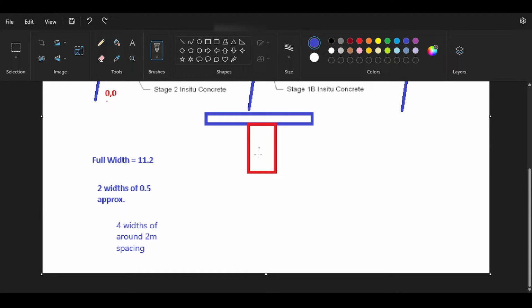Now the beam is a pre-stressed beam, so the cracking will be limited because we will see this in the future, but the stresses are controlled in such a way to not exceed the cracking stress of concrete for the pre-stressed beam. However, for the slab, you have simple reinforced concrete, meaning that the slab might crack. Now, when does the slab crack? The slab cracks if you have a negative moment, or as they call it, I think it's called a hogging moment. Because that's our bridge now, that's what you will have for moment diagram in a bridge.